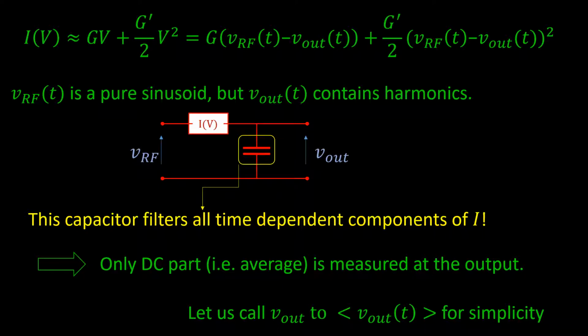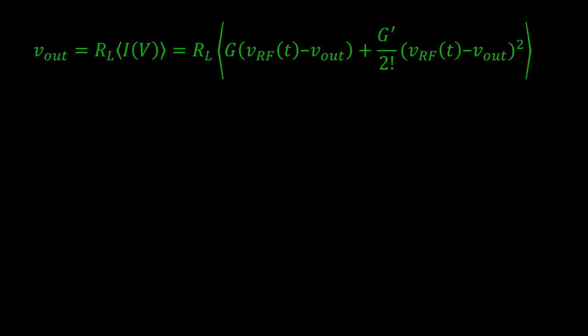In other words, Vout can be assumed to be constant. Therefore, in the forthcoming equations, we will remove the time dependency of Vout. We need to convert the current we have calculated into the voltage we will measure. To do so, we must take into account the input resistance of the instrument we use for the measurement. Might be an oscilloscope, but a multimeter will always offer better sensitivity. Anyway, let us call this resistance RL, since it is actually a load resistance.